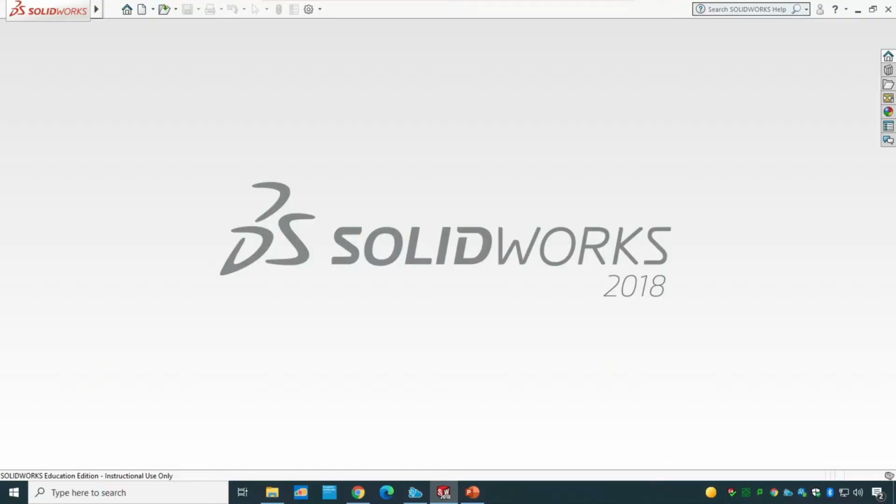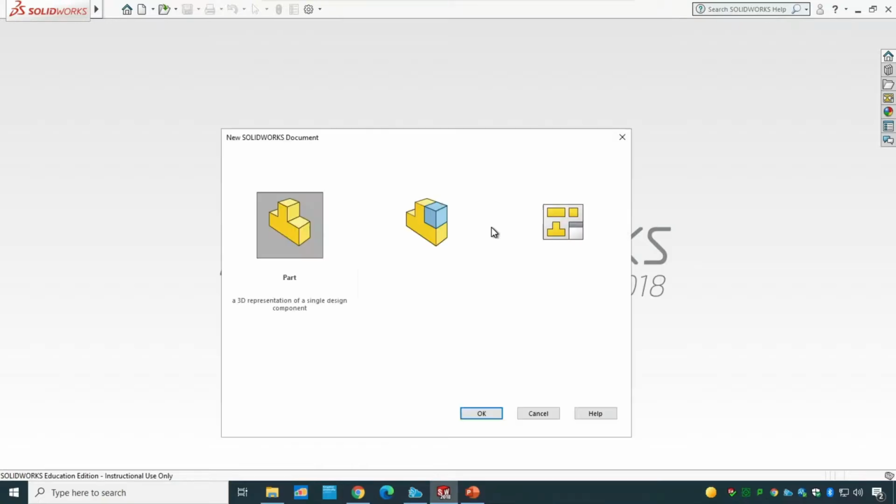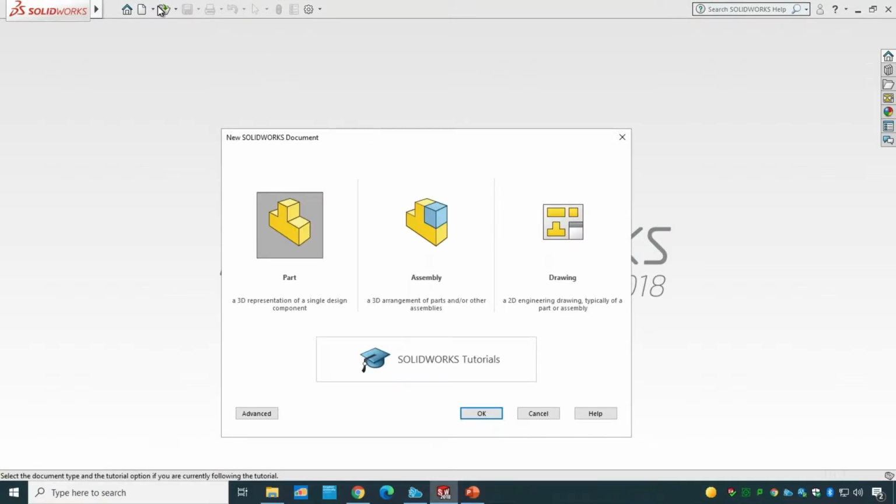So for the first experiment, we're going to start with the laminar pipe flow, and we want to do an internal flow analysis. What I want to do is prepare my geometry to be able to apply that CFD analysis on it. So I'm going to go to SolidWorks, make sure SolidWorks is open, and create a new part file. You can use Control N, or you can go and create a new file on top, and it's a part, and I'm going to click on OK.